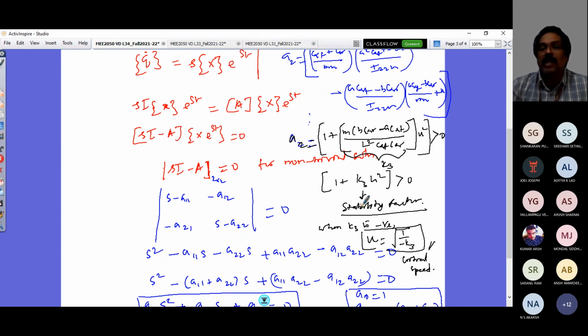And that's what you have learned, and you have looked at it in the bicycle model, and you are able to recognize that the stability factor we were talking about at the beginning comes in here to impose the condition that the critical speed depends upon the vehicle parameters, wherein it depends on its mass and dimensions and the cornering stiffnesses and so on. All right. So this is what you understood.